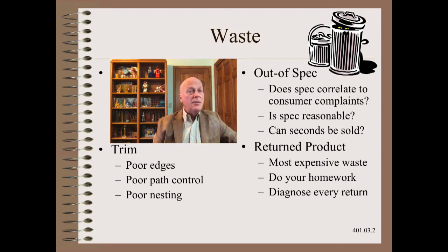However, the waste that costs more dollars per pound than any other is customer complaints, claims, or returns. For one reason, you put more time, materials, and energy at the end of the process than waste taken upstream. Another reason is that you add transportation costs to the customer and back from the customer. Another reason is that returns are often the subject of many hidden costs, such as phone calls and meetings and trials, and capital expenditures to try and reduce complaint.